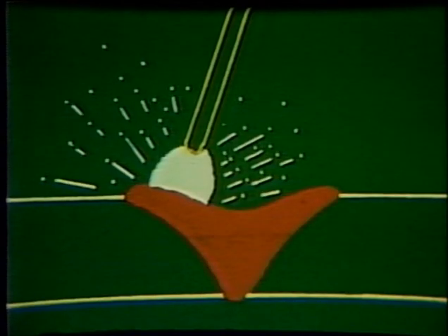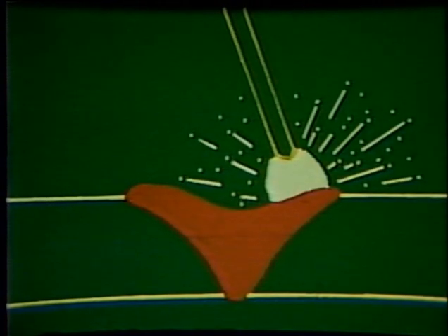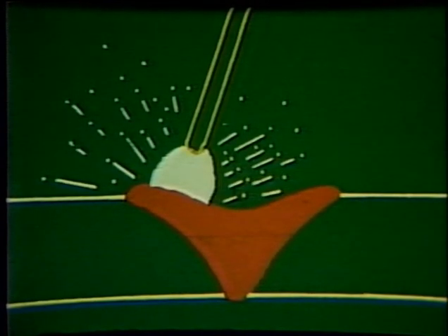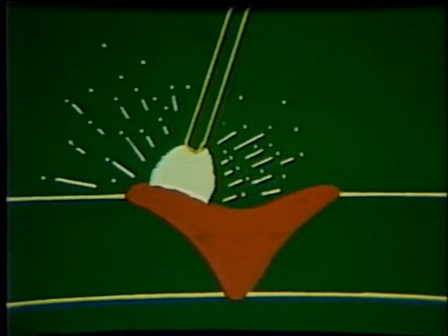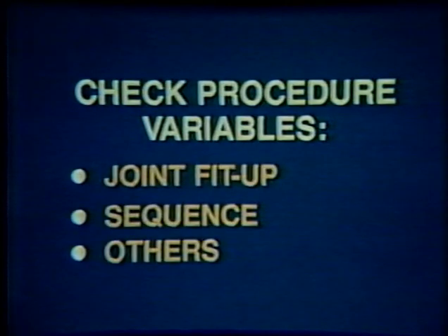The face of a weld can become concave when too wide of an oscillation is being used. This occurs when an overly large puddle is created in an attempt to deposit a relatively large or wide weld. If underfill is a problem, the welding procedure should be reviewed in order to assure that the proper joint fit-up, weld sequencing, and other variables that prevent underfill are being followed.